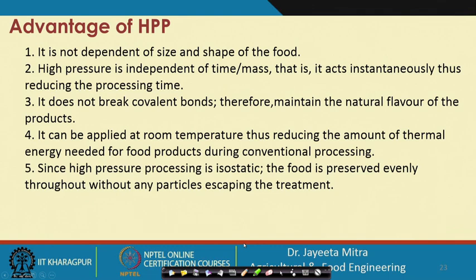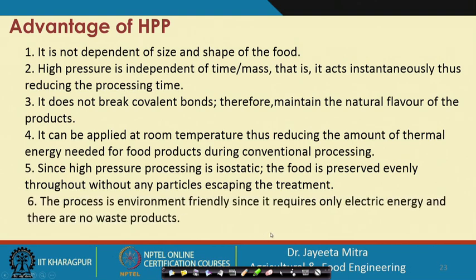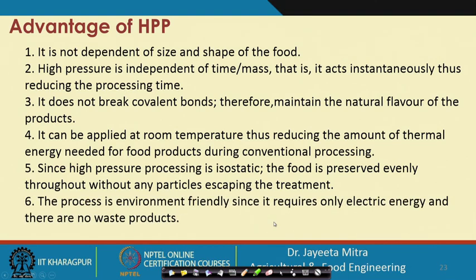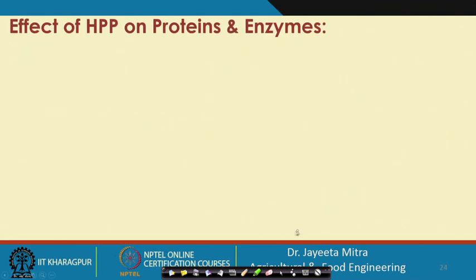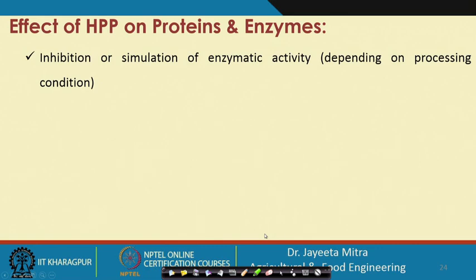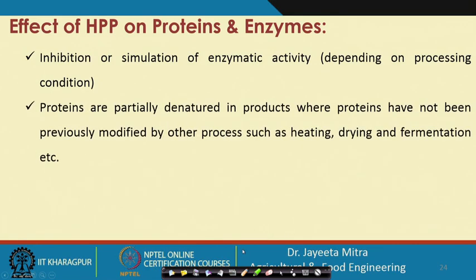Since high pressure processing is isostatic, the food is preserved evenly throughout without any particle escaping the treatment, and the process is environment friendly since it requires only electric energy and there are no waste products generated. So, that way it is very helpful. It has some specific effect on proteins and enzymes, inhibition or stimulation of enzymatic activity. So, it depends on the processing condition, how much pressure we are providing and how long we are providing it.